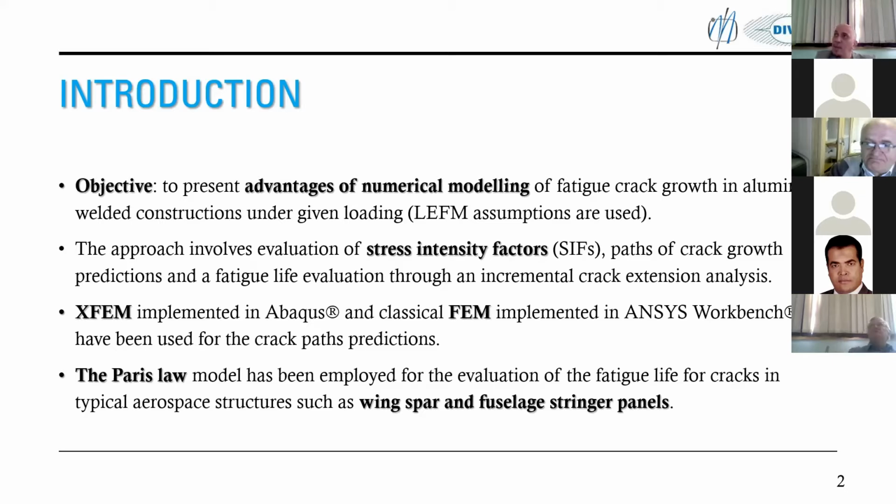And finally, using these values of stress intensity factors and using some of the laws for crack growth, like Paris law, we can estimate the fatigue life of a damaged structure. Here I'm going to present typical aerospace structures like wing spar and fuselage stringer panels.